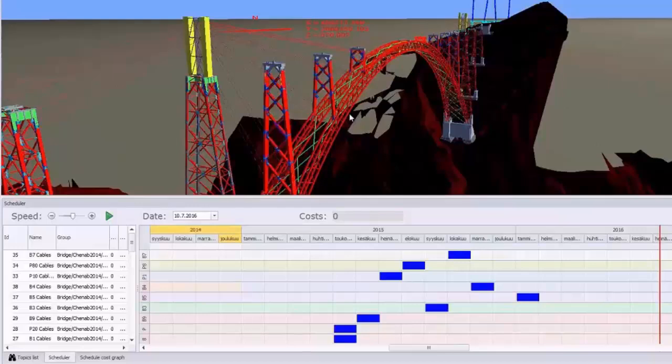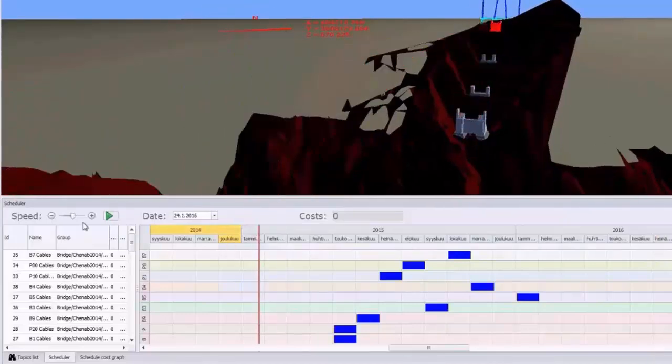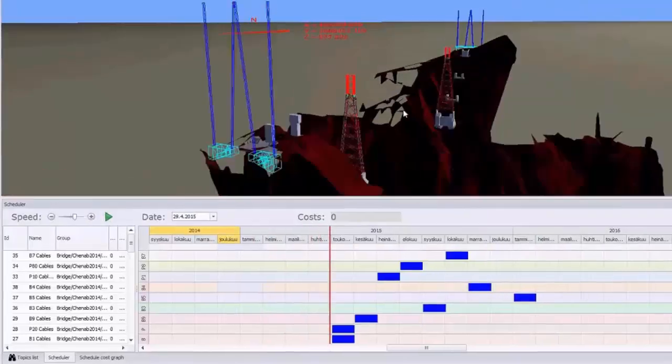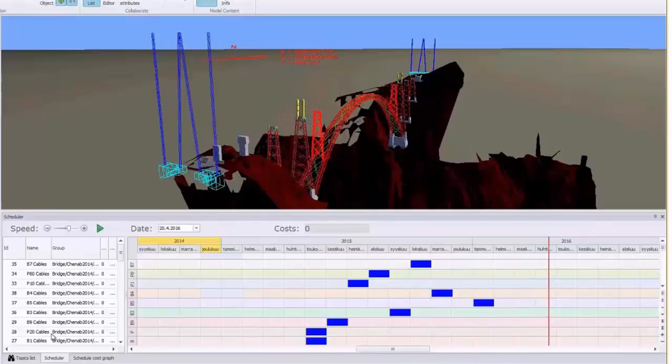You can go to any time and also press the play button, so you can see that. And this is quite easy to make. With Novapoint DCM, you can import your model here, and you can automatically create each task in the model, which will automatically have a line in the 5D, and you can just drag and make your schedule here in real time.